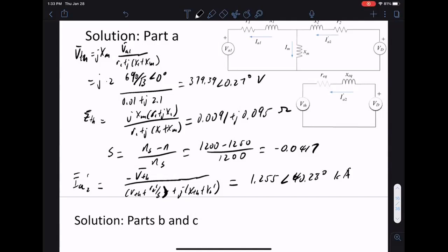Right. So again, the thing is to remember to divide by √3. No matter how many times I say it, at least one of you will not do this in the midterm, and you'll be unhappy because you lost 2 marks if you forgot to divide by √3. So please divide by √3, right? In all these types of equations, to convert the voltage from line to line to line to neutral.